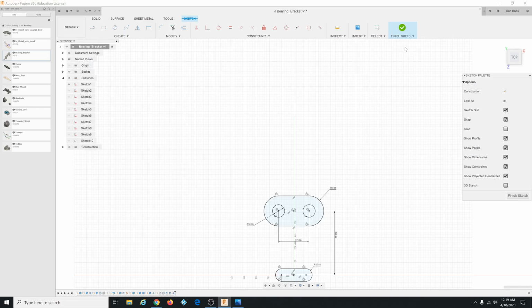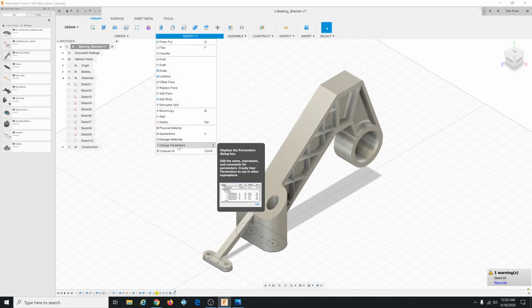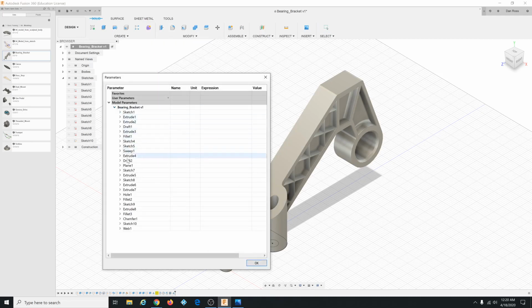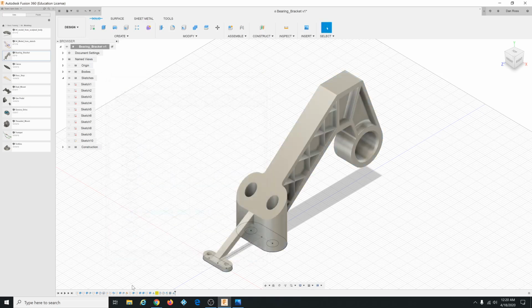it's thinking. There it goes. Then the hole that was extruded from that sketch gets smaller, right? So that's parametric. You could also find that hole in this change parameters thing. You could dig in here and somewhere in here is that hole, and you could change the value, right? So you could do that. You could also find the hole, whatever you're trying to do in here, you could find that operation and edit it. Okay, and that's what we're going to do.